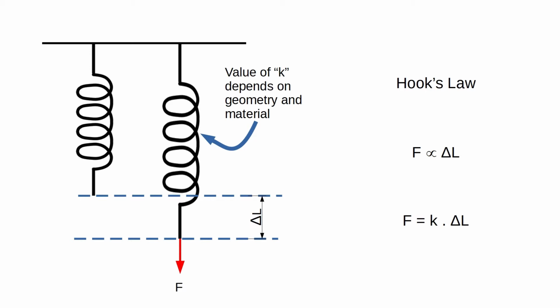If not, either we would be optimizing its shape by finding stresses generated in the object due to applied loads. For example, the objective of the study can be to optimize web thickness of gussets or optimize thickness of a pressure vessel nozzle saddle. Or we would be checking which material is most suitable for the given object. For example, the objective of the study can be, can aluminum alloy be used to reduce the weight of the object while keeping the stresses within limits? So, stiffness K would be fixed for the given analysis based on shape and material selected.